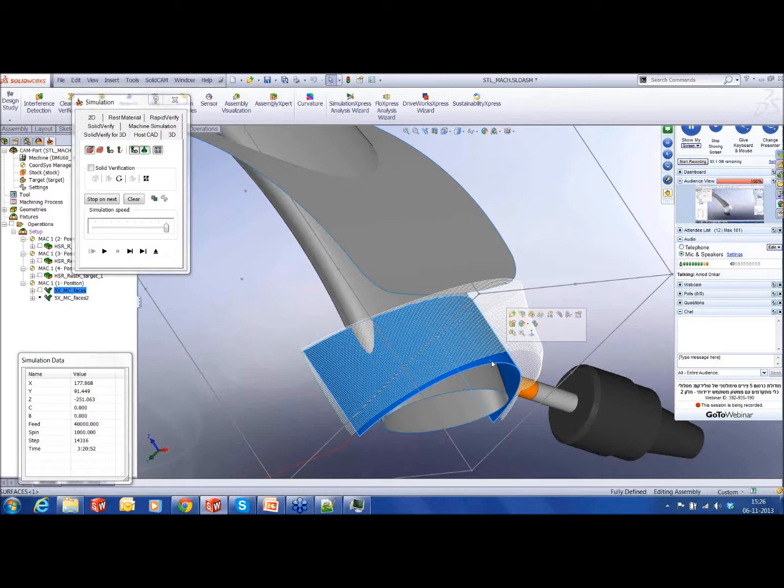So what we did was we basically selected the bottommost surface, we created the toolpath, and just then projected this toolpath along the tool direction on the STL geometry. Very easy, very simple. And you can use shorter tools to cut any kind of STL geometries without having to convert them to any kind of surfaces. So if you really want to cut, let's say, scanned parts done by white light scanning or even probing, you could directly take the STL geometry from the scanner and start cutting in 5-axis straight away.